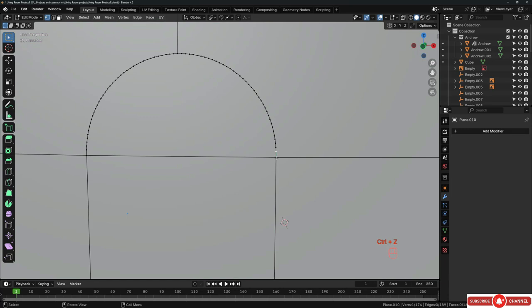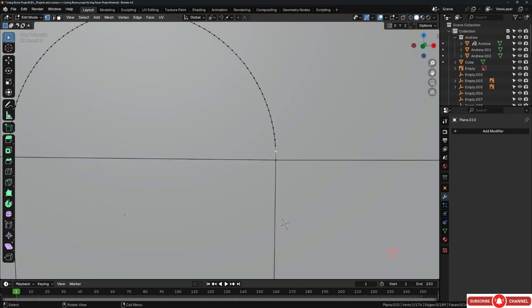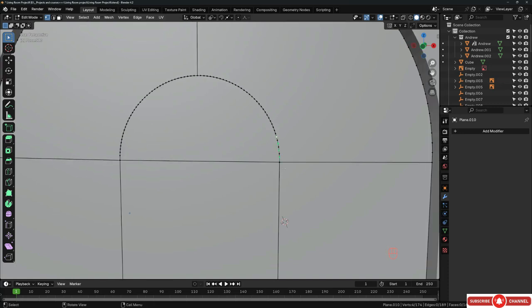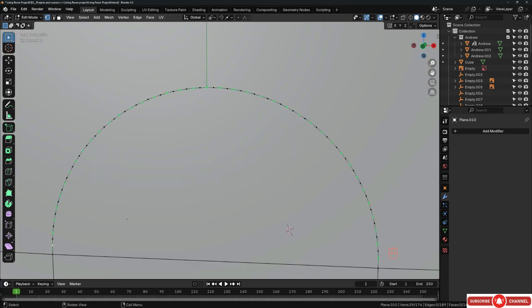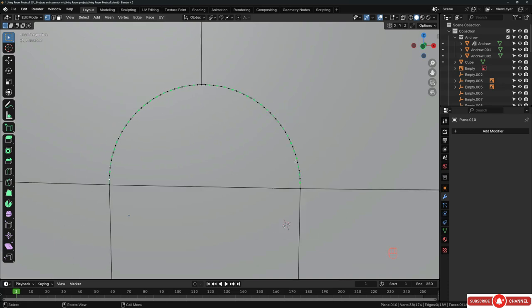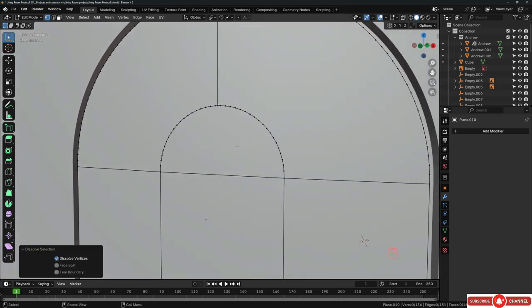All right, that's very cool. We can do that. So let's start with this vertex. Hold Shift, leave 1, pick 1, and let's do that again and again. And if you want to speed this up, hit Control, Shift, and plus multiple times until you reach the other side. All right, something like that. And I don't want to target this vertex. Hold Control and deselect it like that. And then hit Control X to dissolve these. And I think that's it.